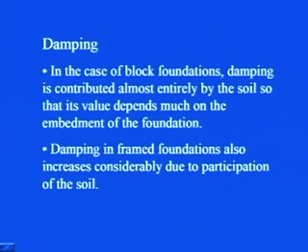In the case of block foundations, damping is contributed almost entirely by the soil, so its value depends much on the embedment of the foundation. You have seen that in a block foundation, a concrete block is cast, and on top of that the motor and the machine are mounted, and its mass is also very heavy. So, since we are discussing the block foundation, the damping in that system will be mostly contributed by the soil on which the concrete block rests.